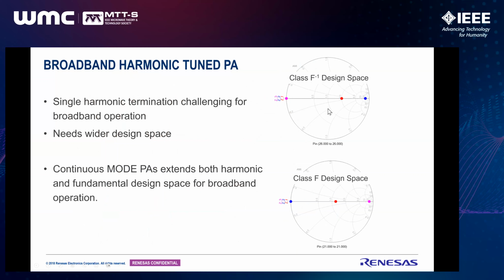And if we normalize it, we can represent that normalized voltage like this. From that point, we introduce two parameters: gamma and phi2. By gamma, we mean V2 over V1, that is, how much second harmonic voltage we are considering compared to the fundamental input voltage. And phi2 is the phase difference between the fundamental and the second harmonic component.